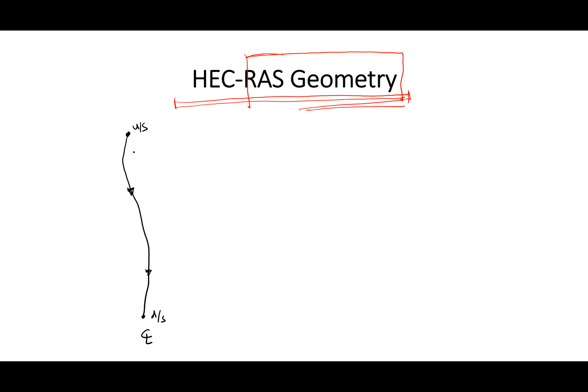When you define the geometry, the first thing you do is define the center line, and you always digitize from upstream to downstream. So center line, always digitize from upstream to downstream. I will again explain this when we do the HEC-HMS lab.